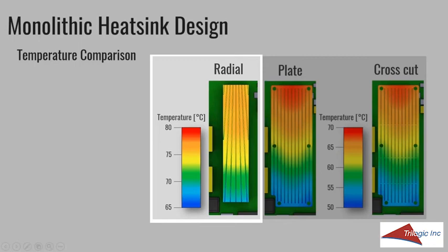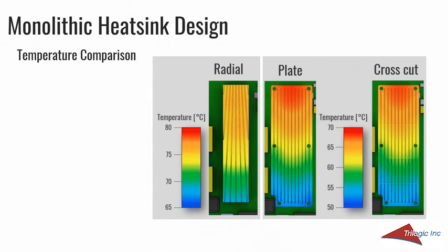Now, these fins are not optimized. You could probably try more fins, less fins, different angles, and look at the effect. What we wanted to begin with is to see, did this initial sketch on a napkin warrant any further investigation? Our decision was that it really didn't, but it doesn't mean it was a bad design. It's just that it's probably going to be hard to improve over this base performance.